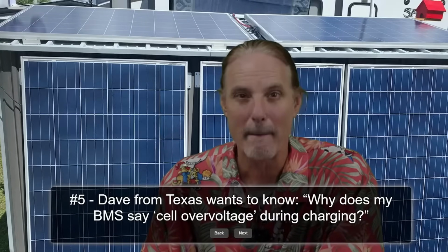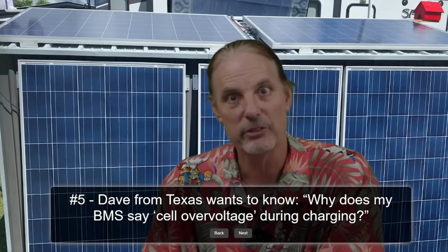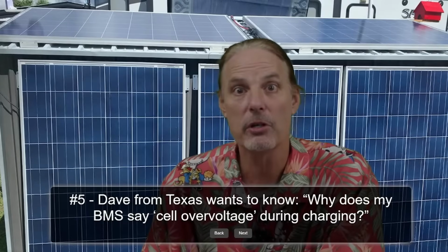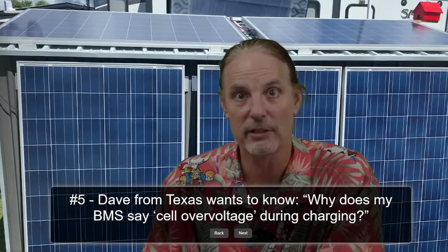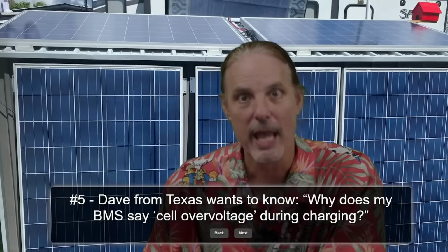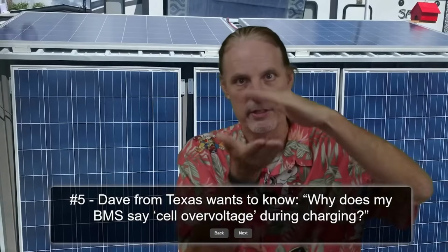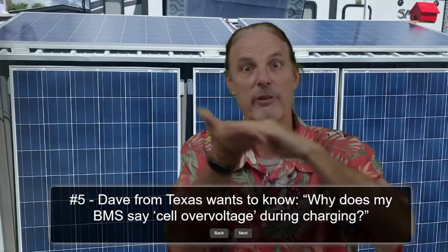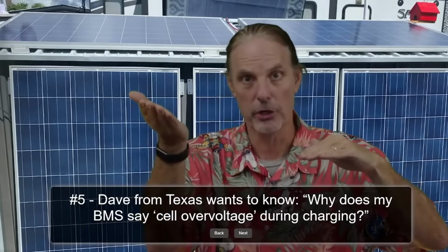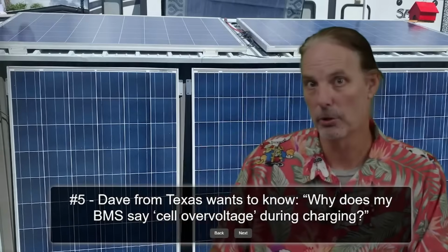And this is why balancing is very, very important, because if you leave it in that state long enough to allow for that balancing at some of these voltages, it'll actually pull that cell down and bring up the lower cell, and thus reduce the difference between all the cells and allow you to get a fuller charge and to fully use the capacity of all of your batteries.